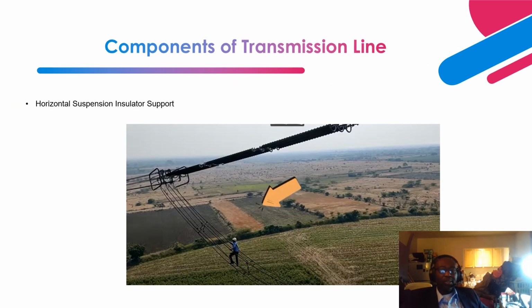It's a horizontal suspended insulator, right? Okay, so like I told you, as you can see over here, this is basically made of 3 of them in parallel, right? And they've been put together, stacking up all the way, based on the transmission voltage level.